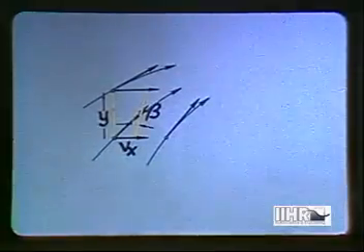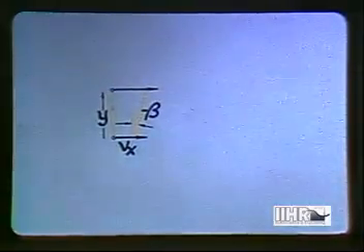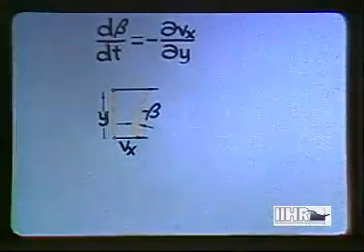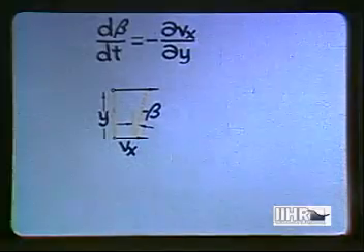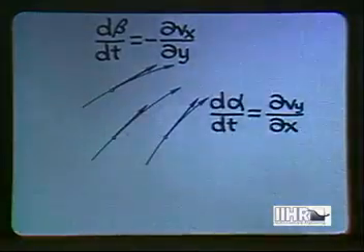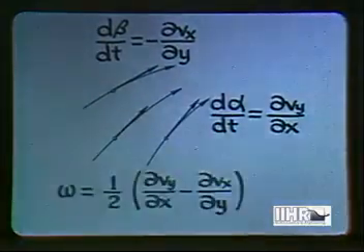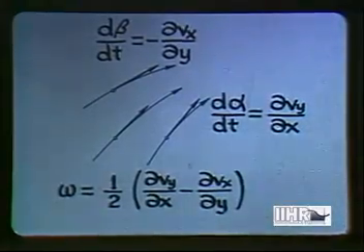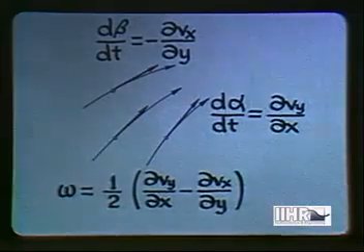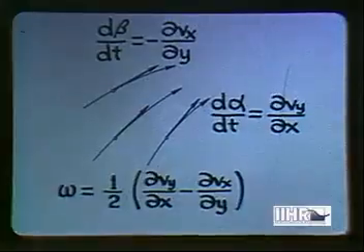The same is true of a line or stick in a direction that is perpendicular to the first, a negative velocity gradient now indicating rotation in the same positive sense. The net vorticity in a given plane depends upon the average of the velocity gradients in the two normal directions. This in turn would be indicated by the average tendency of two lines or sticks at right angles to each other to rotate. In the case of water in a tank rotating about its axis, the velocity varies directly with the radius.